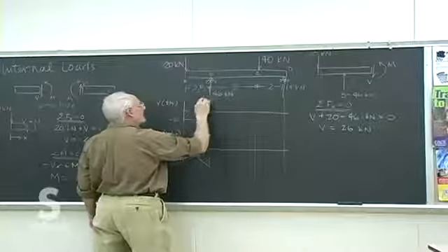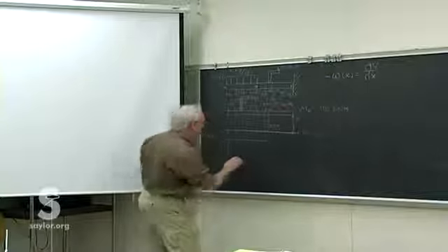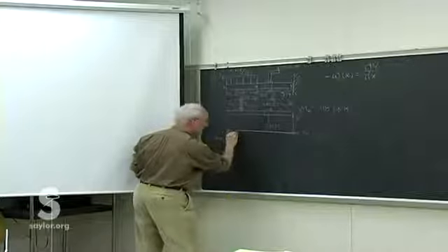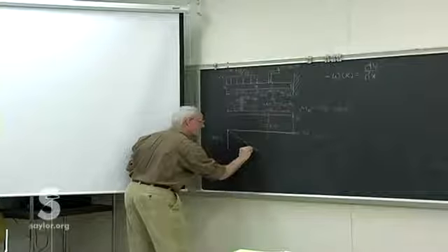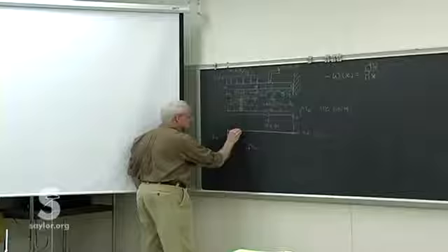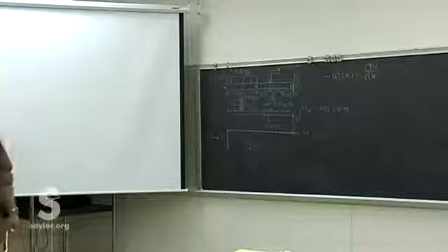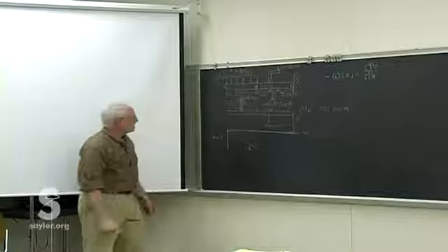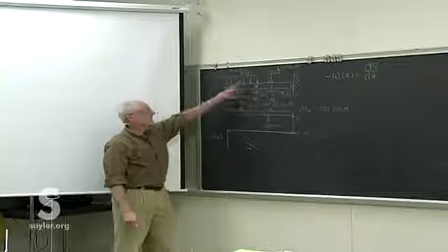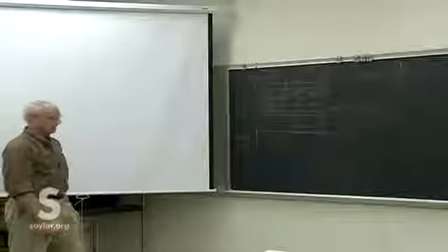So we have a negative slope of 3 kips per foot. And that would go for 8 feet, so it would take us down to about 24. So I can leave enough room. Is something like that. And we can do that remembering this relationship between the shear and the distributed load without having to actually make the internal, the imaginary cuts and figuring out the internal loads there.